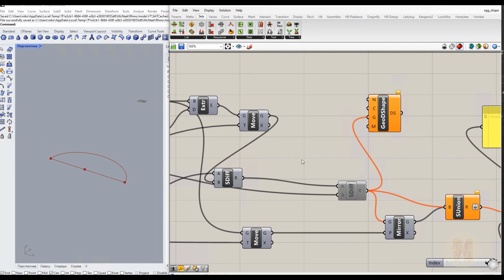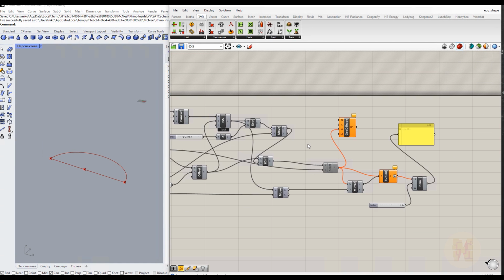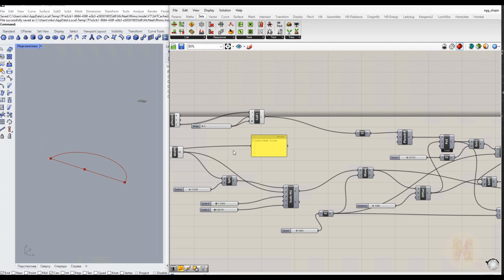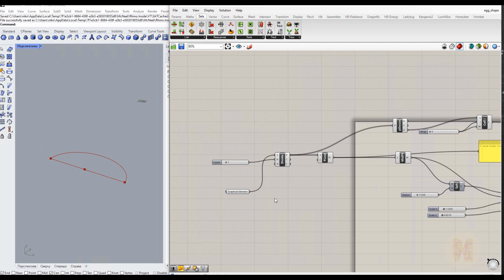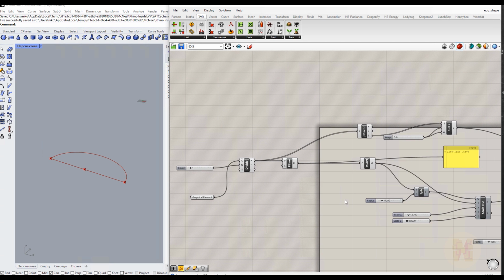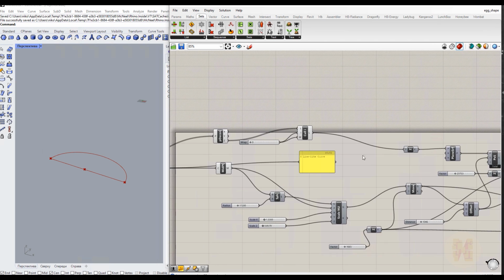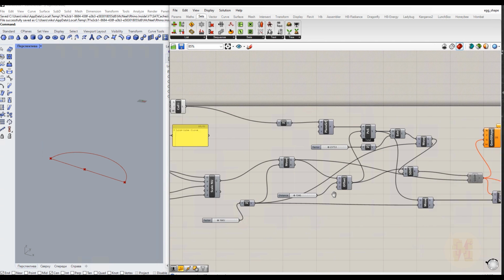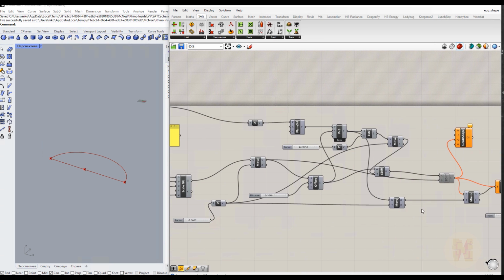So guys, in this tutorial we covered a lot of different things. For example, how to find our geometry from Revit, how to find and use the midpoints, how to move it, how to use different solids, everything. Of course, we can create our shape in Rhino, transfer it to Revit, and manually change, for example, the position in Revit.